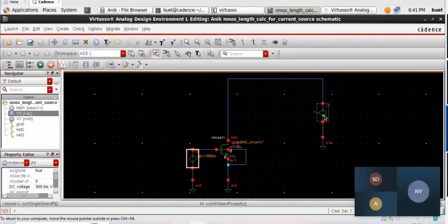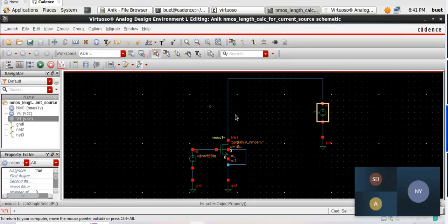AC source. Now here this itself is acting as an input. So this voltage divided by the current that is generated by this particular voltage source, which flows through this MOSFET, together will fetch me the resistance. And because you are connecting this source at the output side, whatever resistance you obtain in this scenario, I can call that the output resistance.